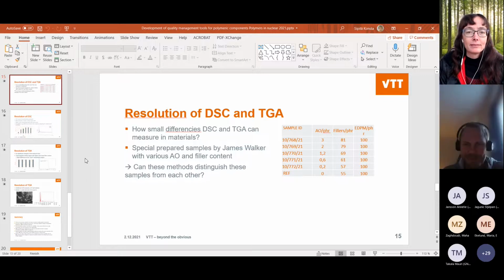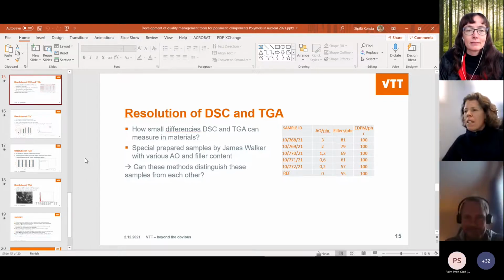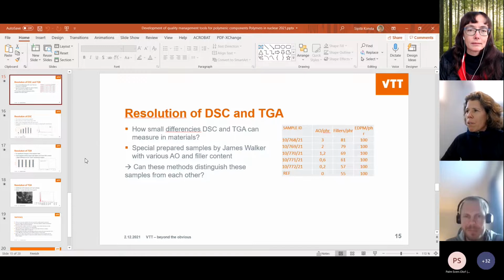Karin: Yes, I'm just wondering about the DSC and the OIT, because normally that's for polyolefins, and what would the difference be if you have two different types of EPDMs? We also know that two different types of hindered phenol stabilizers give different OITs even in the same material. Have you looked into that at all? I don't think it's been used so much in elastomers.